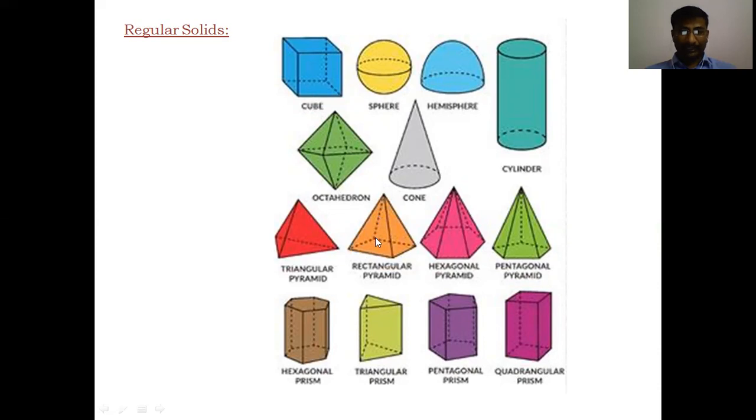which is located as a dotted line here. And the base also has 2 sides visible, a rectangular base, and another 2 sides are invisible, because these 2 sides are the back side of the solid, therefore they are drawn with dotted lines. These 2 lines are dotted, and this slant edge is also dotted because these 3 lines are invisible when looking from the front side of the solid.